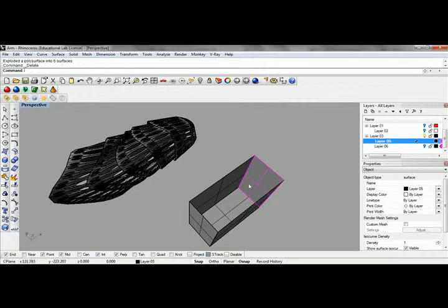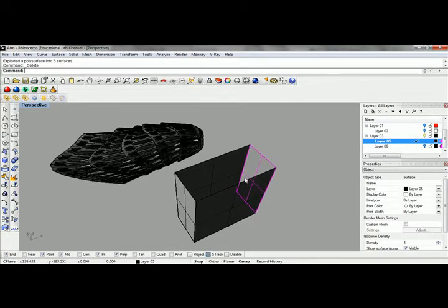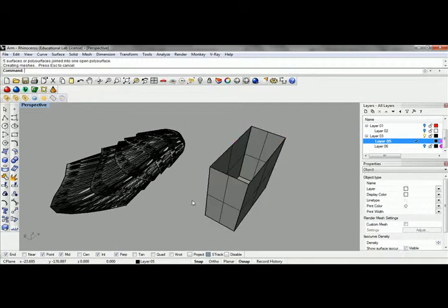So whenever we model a geometry that's going to be taken to a 3D printer, we want to make sure that that geometry is enclosed on all sides. It doesn't matter how many sides, it's just that it needs to be fully and completely enclosed and have a distinct inside and a distinct outside. So I'll rejoin that because we'll use some of this geometry later when we get into some of the analysis tools.